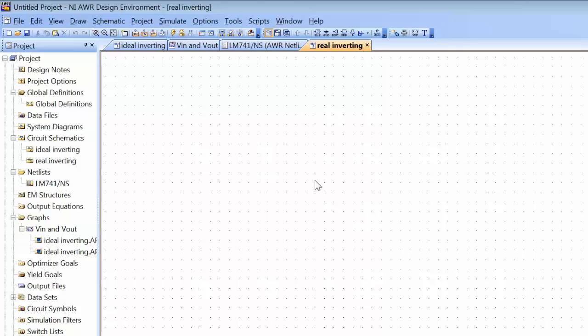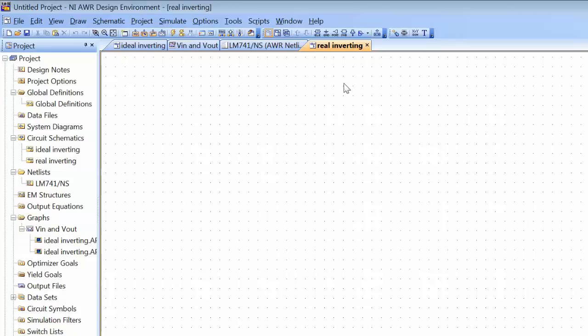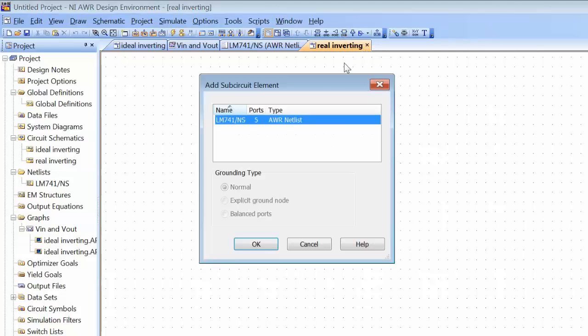And then, in this case, we won't press Ctrl L, we either press Ctrl K to select the sub-circuit that you see here, the circuit that we've imported, or simply click on the sub icon up here, and a list of the sub-circuits available will be displayed.